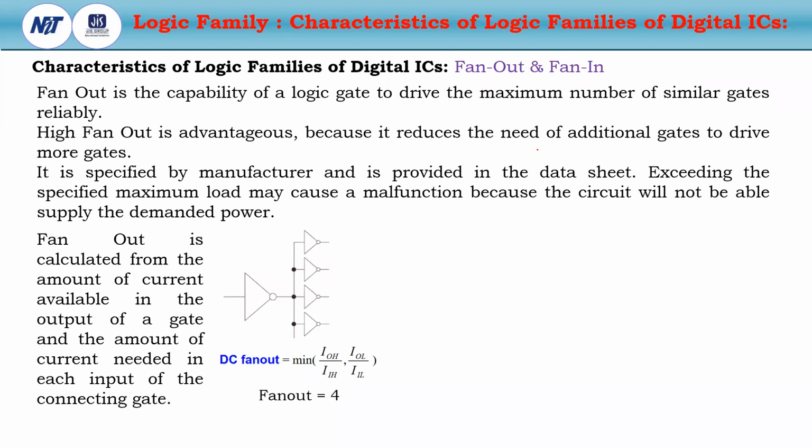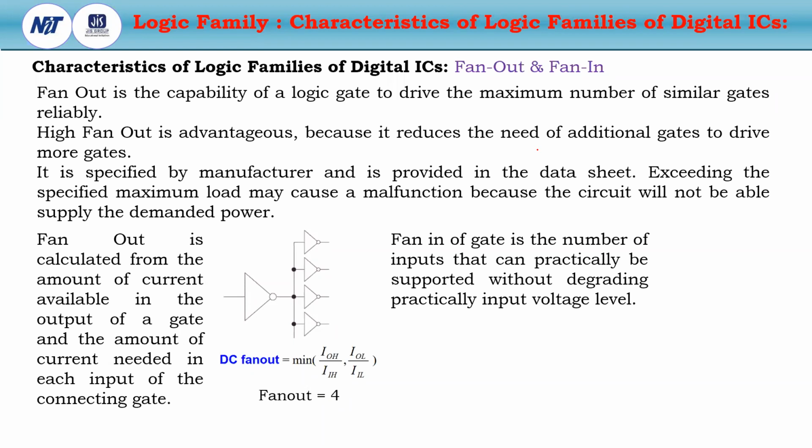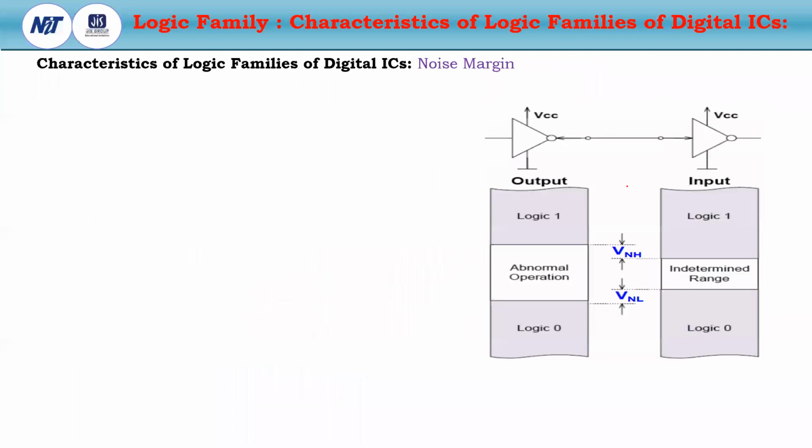So that is very important. The fan out is specified by the manufacturer and it is provided in the data sheet of a particular digital IC. Exceeding the specified maximum load may cause a malfunction, or the circuit will not be able to supply the demanded power.